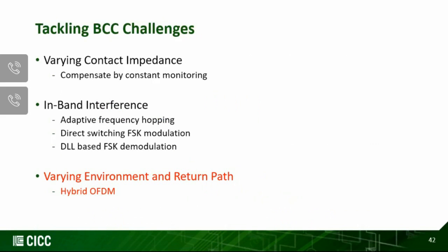Okay, so that brings us to the last challenge in the transceiver design of the BCC, yet it's the biggest problem in the capacitive coupling-based BCC. That's the varying environmental change and return path, which can be mitigated by the hybrid OFDM.